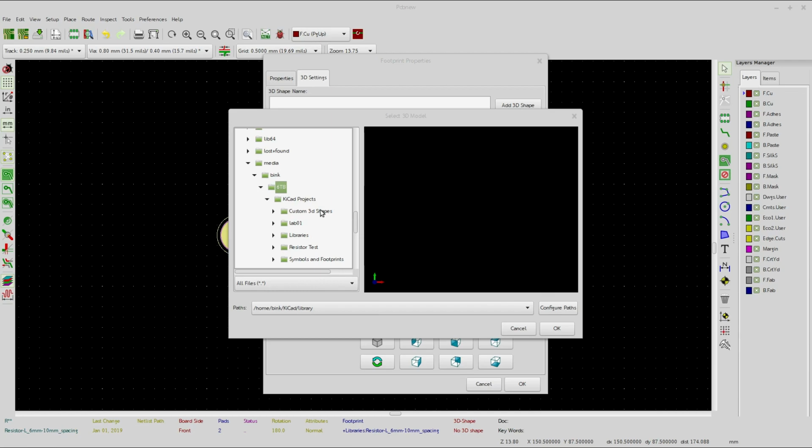So then I can redirect my library location to that memory stick. Every time I'm here and you see me going through the whole tree structure, or it navigates to its default section and then I go somewhere else, that's not the normal way to do it. If you put everything in one single KiCad directory and you rewrite your paths accordingly, then it'll just pop right up there.